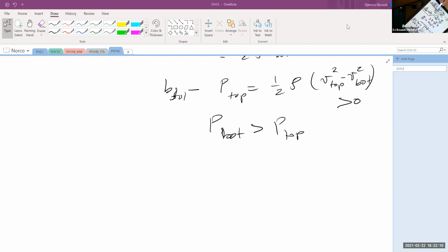Here is the deal. I'm going to integrate from h equal to 80 centimeters, or 0.8 meters, down to when h is equal to 0, when we've completely drained this thing. So those are my boundaries of integration. On the other side, the integration of t is from 0 all the way to the time T when this thing is drained. So on one side, I will find big T. On the other side, the integral starts from 0.8 and comes down to 0. And I'm going to integrate this square root of h in here. So all I have is an h in the denominator, and make your change of variable and take the power, the integral of x to the power 1/2, and so on and so forth.